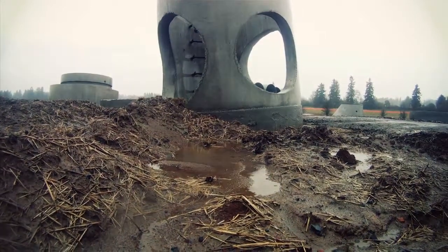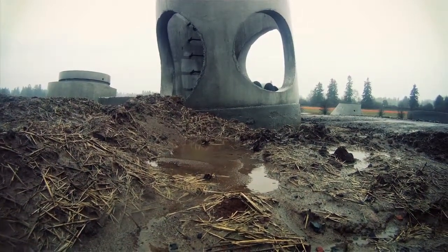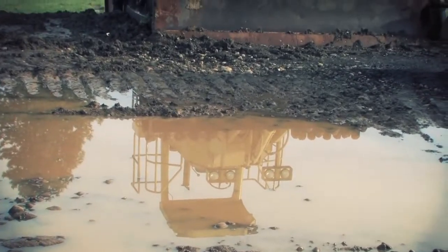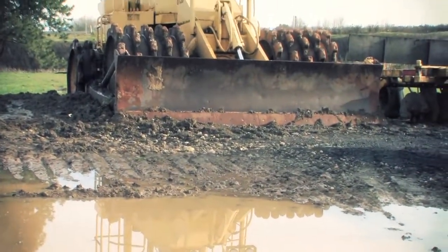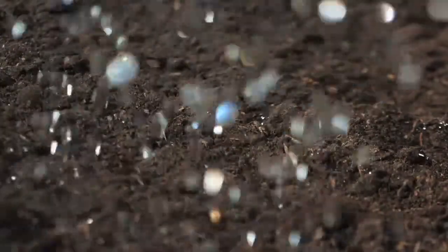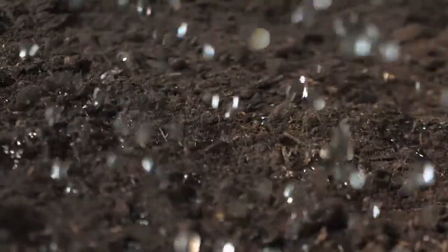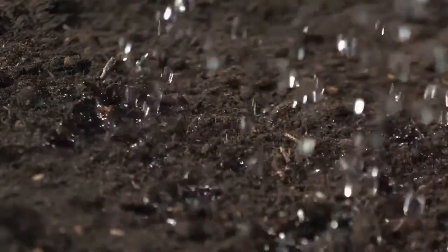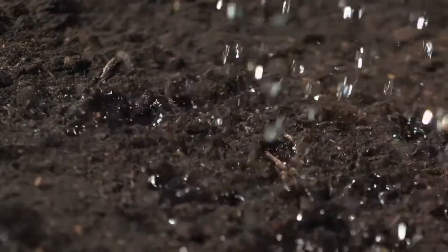To determine the soil type on a construction site, there are several tests that can be used. Following a visual test, a plasticity test can determine if the soil is cohesive or granular. For cohesive soil, the thumb penetration and pocket penetrometer tests help determine the unconfined compressive strength. Determining the type of soil on a site will help to decide which methods of sloping, benching, or shoring are needed to prevent cave-ins and keep workers safe.